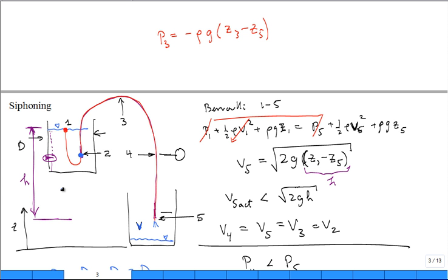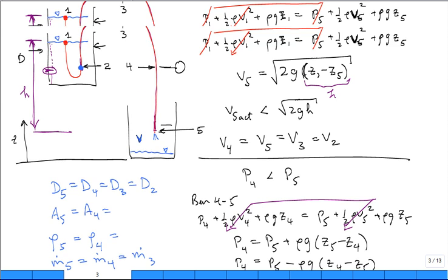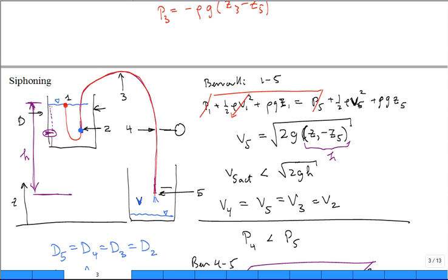And if you get the siphon down, maybe you're a long way to applying Bernoulli's to a lot of other problems. If I wanted to get the volumetric flow rate, or the mass flow rate, it is the mass density times the speed times the area, true? How would I get it to drain that tank faster?